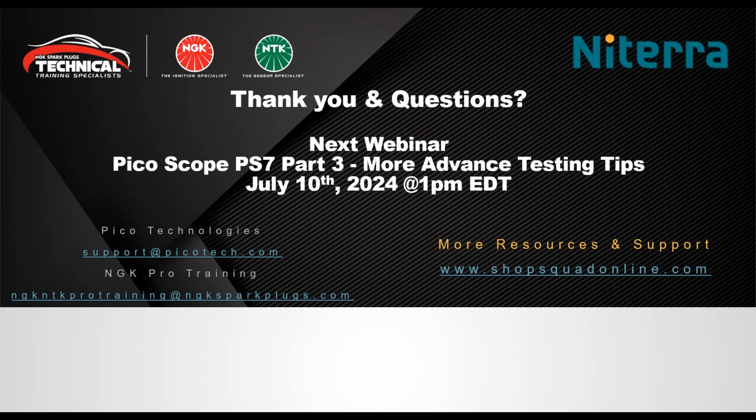All right. The next question was related to a new amp clamp, the TA408. It's only the BNC plus. Correct. The 408 has a very wide jaw. The jaw size is very similar to a TA388. So it's got the jaw size of a high amp clamp, but it's limited to 100 amps.